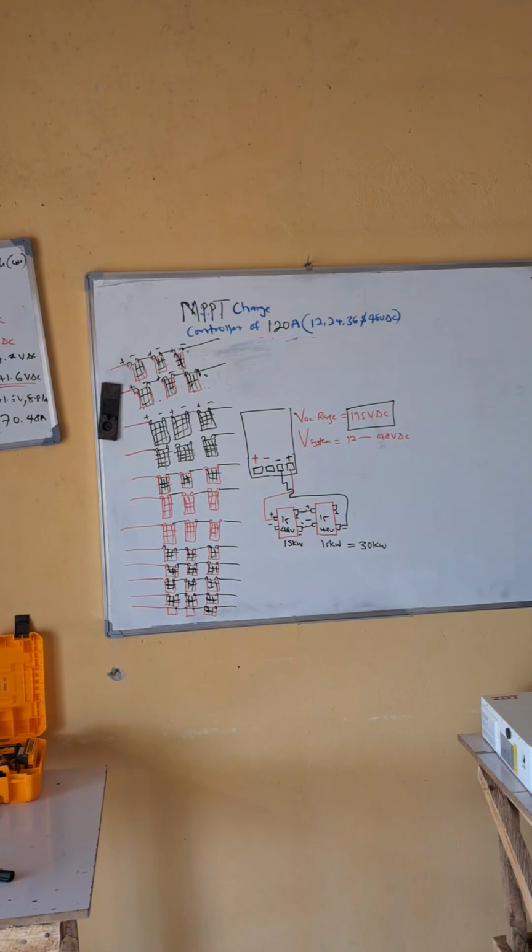So now if you look at this illustration, we have each string of 3 panels containing 350 watt panels. They are all connected in series. So each panel will obtain a VOC of 37.2, which means times 3 it will get 111 point what? 37.2 times 3. What do we have?